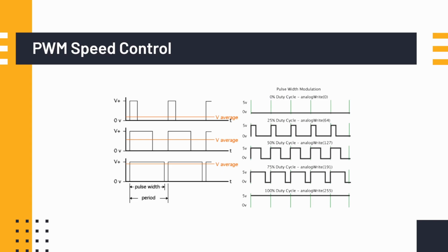And then let's say you want your motors to spin a little bit faster, but not at max speed. You would increase it up. So let's say, what does it say? Your 25% duty cycle, right? So it sends out the electrical signal in short pulses to gradually move the motor. And then these electrical signals eventually become greater and greater in terms of their pulse width, until eventually you get just like a continuous electrical high, and that's basically telling your motors to go at full speed.